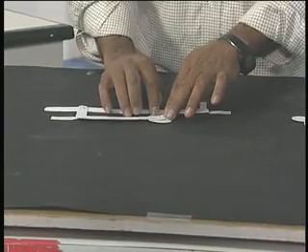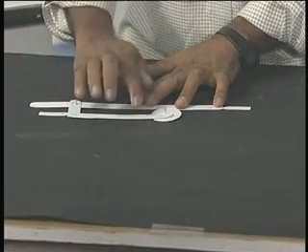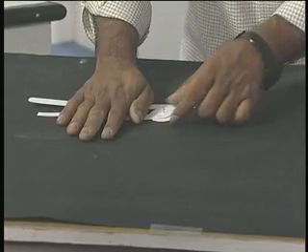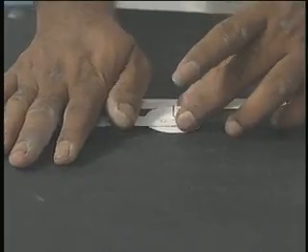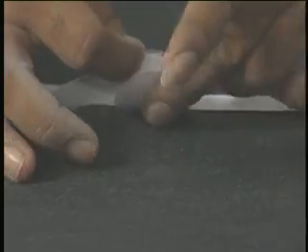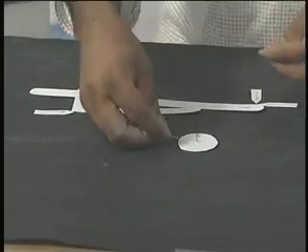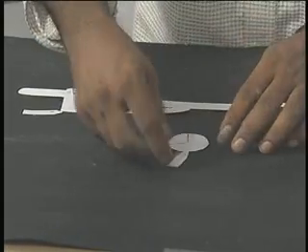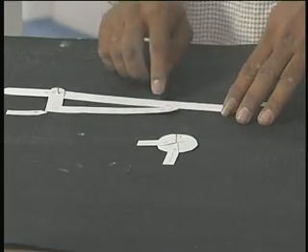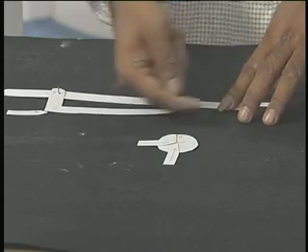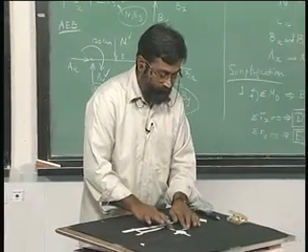Supposing I have to remove this particular planar body from the system, I need to fix AB and fix BCD. So this point D, pin at point D does not allow it to move. So what I am going to do is I am going to now remove this and insert two forces that prevented movement at D. Okay. In addition, there is at this point E, there is horizontal and vertical restraints. So I can add those two.